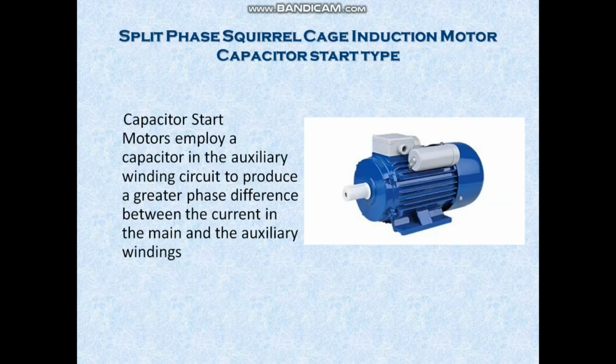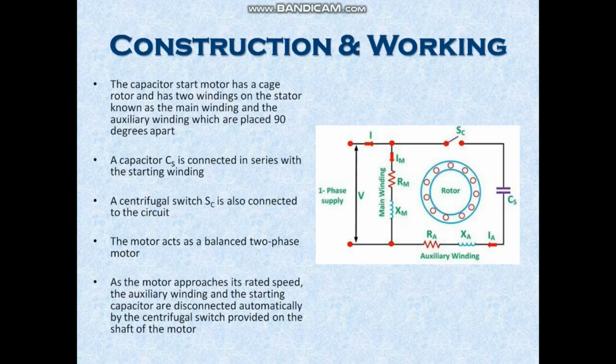Split phase squirrel cage induction motor, capacitor start type. These motors employ a capacitor in the auxiliary winding circuit to produce a greater phase difference between the current in the main and the auxiliary windings. Let's understand the working principle.